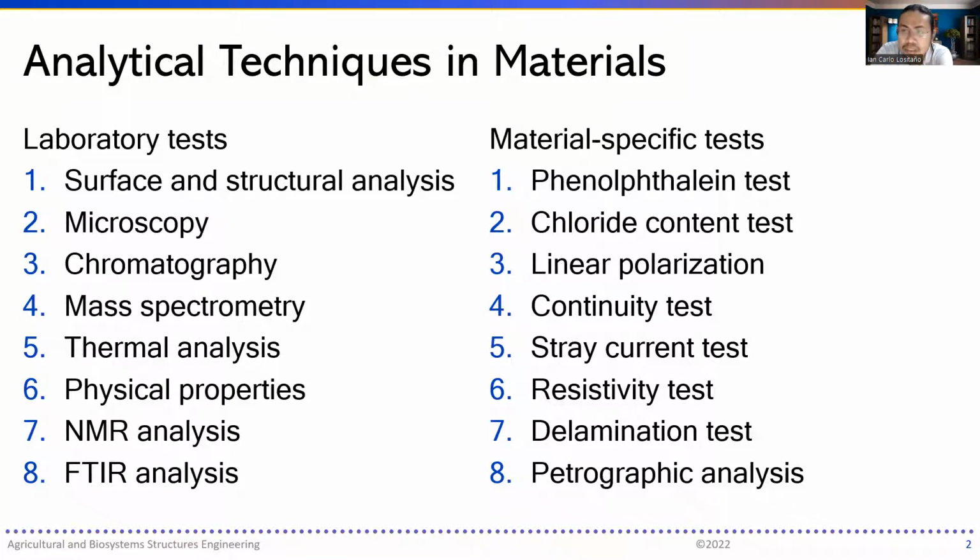In places where there is very high chlorine content in seawater and also in production plants where there is the use of chlorine to sanitize equipment and other materials, the chlorine, because it is unstable, would turn into its gaseous phase and react or corrode the metal in the roofing, the beams or the trusses of the structure or the building.